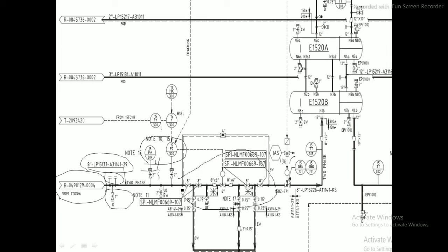Okay, and you can see here we have a control valve, or we have to check in the legend sheet what this symbol means. So what is the symbol exactly? Is it a control valve or some other thing? Because you can see this line is connecting to this instrument item, which means this pressure will get controlled, and it will automatically get operated over here.